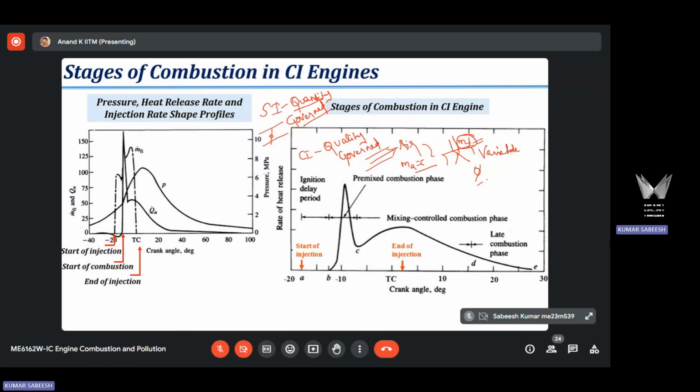That's why we always use this phi to analyze engine operating condition, okay, rather than air fuel ratio, because it also connects the theoretically correct proportion and the actual proportion. So phi represents the actual fuel mass that goes into the engine. That's why we use this parameter often to analyze the engine operating condition. So later on also in the second module, the emission module, we will talk about how the pollutants vary with respect to phi, because phi captures the actual fuel mass that goes into the engine in each cycle. So it's one of the important variables we use to analyze pollutants as well as combustion.